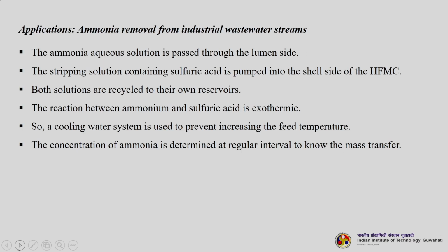Another application is ammonia removal from industrial wastewater streams. The ammonia aqueous solution is passed through the lumen side and the stripping solution containing sulfuric acid is pumped into the shell side of the HFMC, the hollow fiber membrane contactor. Both solutions are recycled to their own reservoirs. The reaction between ammonia, ammonium and sulfuric acid is very exothermic, so a cooling water system is used to prevent the feed temperature from increasing. The concentration of ammonia is determined at regular intervals to know the mass transfer.